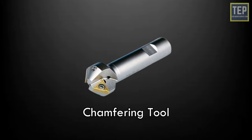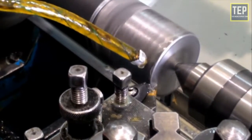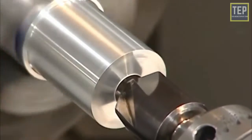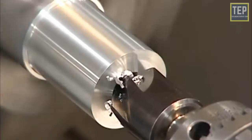Chamfering tool. Straight turning tools are also used as a chamfering tool when the cutting edges are set at the angle of the chamfer. Where a large number of chamfer works are to be performed, a special chamfering tool with its side cutting edge angle ground to the angle of the chamfer is used.